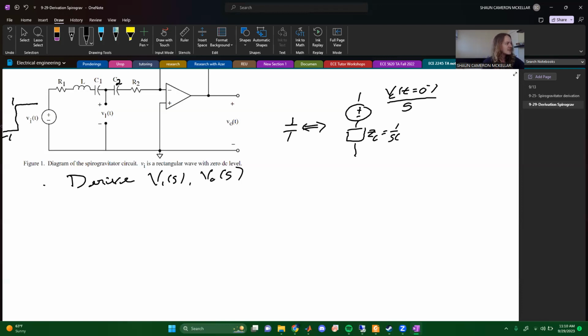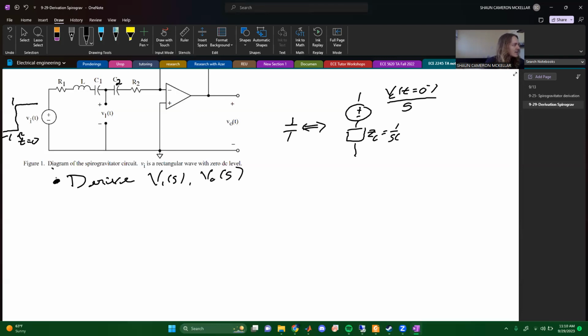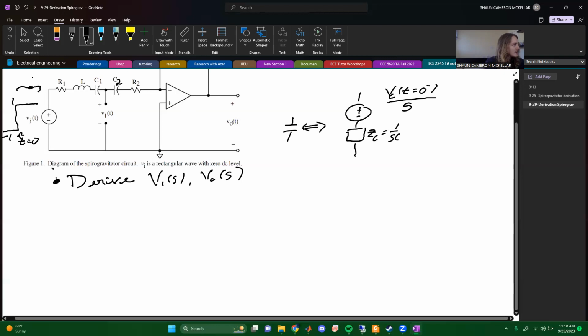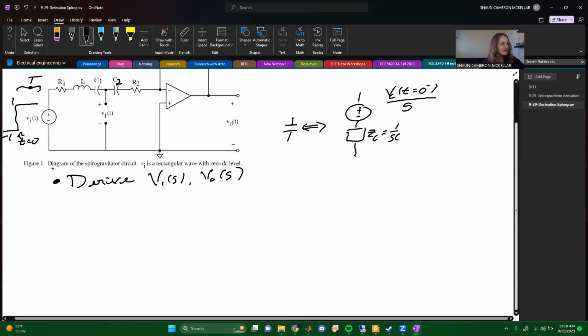It switches at t equals 0 right here, so the capacitor was charged up to -1 volts. The lab handout tells us the period, capital T, is large enough that capacitors can charge up fully each time and then some. We've separated the capacitors into 2 capacitors of equal value, so C1 equals C2.